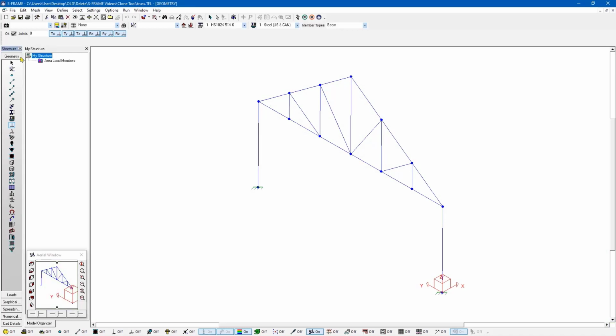And here I'm going to introduce a trick. When we're working with this clone tool, it allows us to clone not only the members, but also the joints. And with the joints that we select, we can actually extrude members from those if we'd want to have members connecting each additional copy. So what I'm going to do is unselect the joints that I don't want to create members between. I'll just unselect the bottom, and then along this bottom edge of the truss as well. So every other joint is going to have a member connecting that to the next frame over.